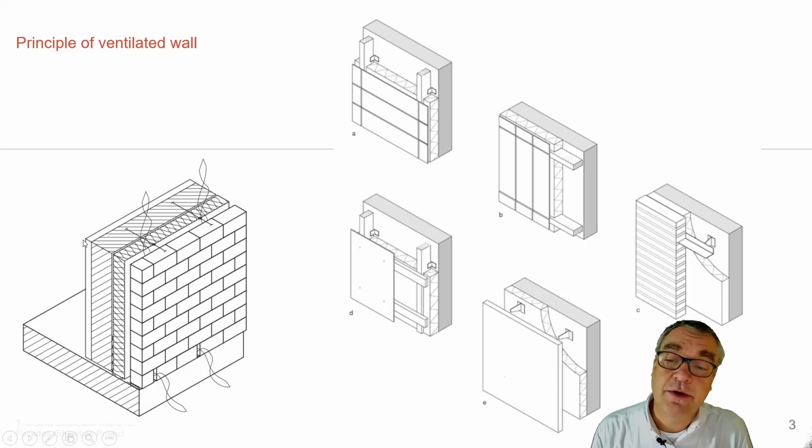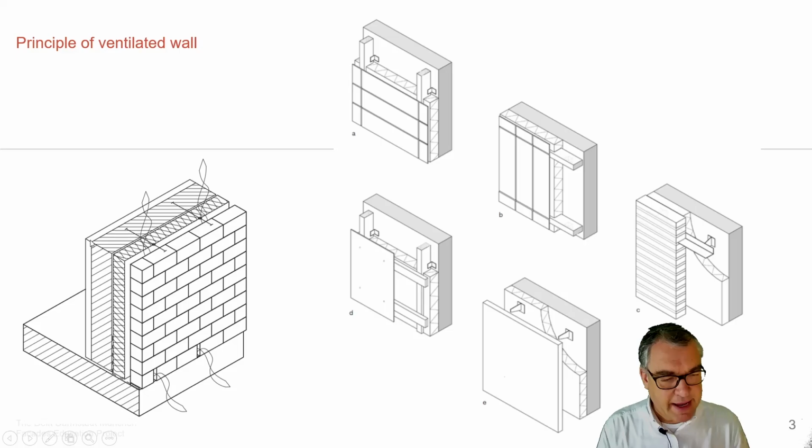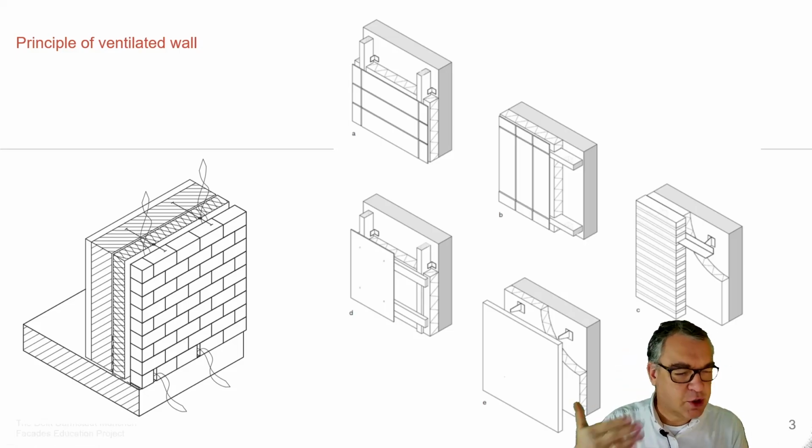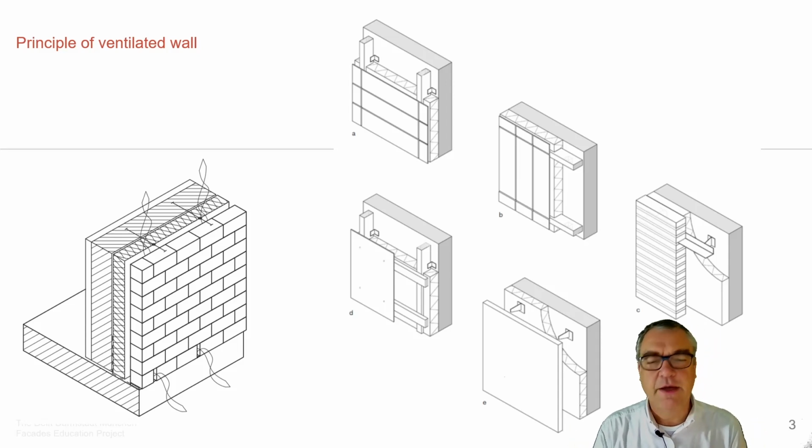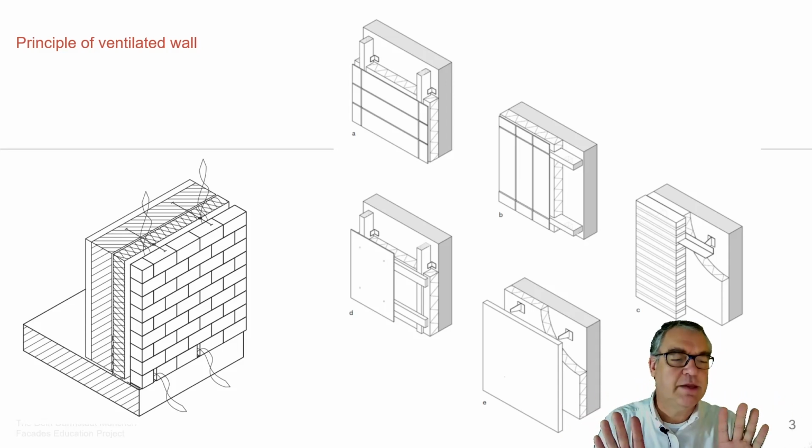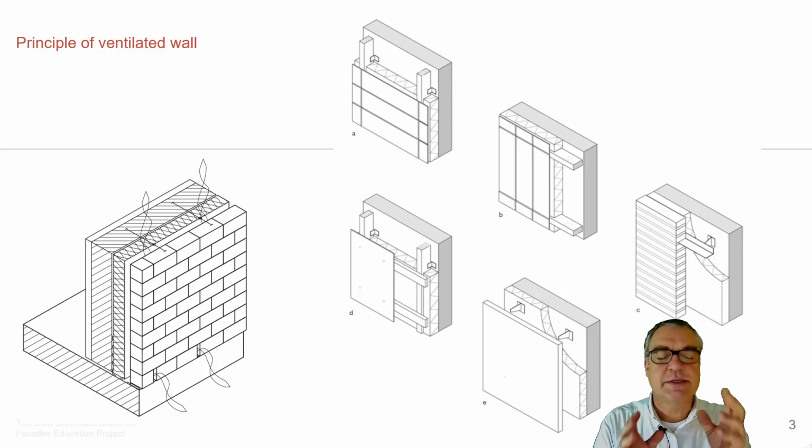And we have the inner airtightness layer, which needs to seal the wall system against humidity from inside, something we need to take care of very carefully to make sure that no humidity from the inside penetrates our system, ending up in the wall. If this humidity ends up in the wall, we need to make sure that it is still open enough, breathable enough, to allow the humidity to get out of the system.